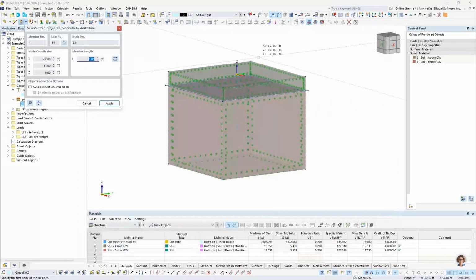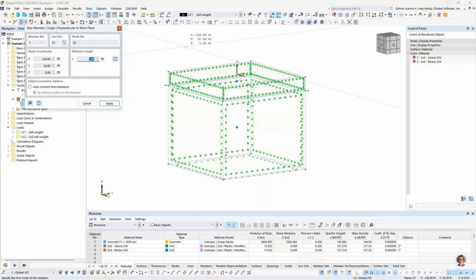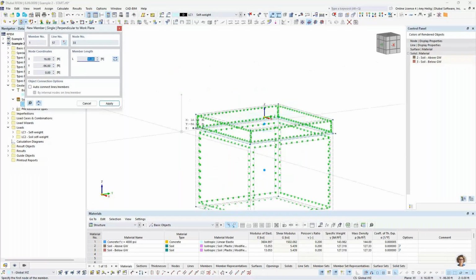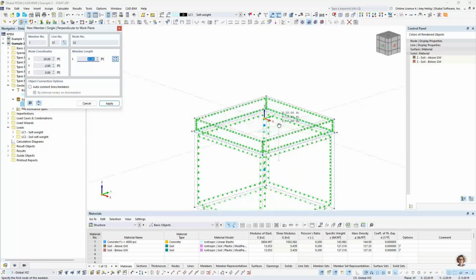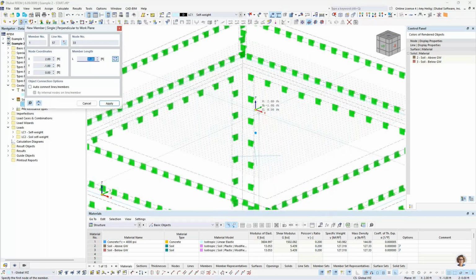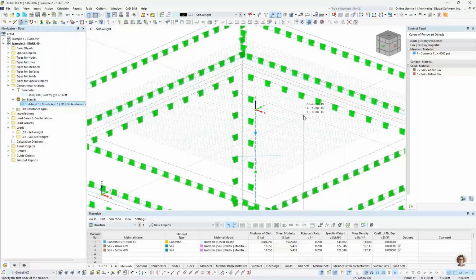Okay, so now that this information is set, we click OK, and we're ready to draw this element graphically within the model. So I'll turn this to a wireframe view, and I'm going to set the member length here to 31 feet. Now notice if I try and snap here, the pile is in the wrong orientation. We can quickly use this button here to reverse that. And then I'm just going to input here by selecting directly at the origin point my pile element.